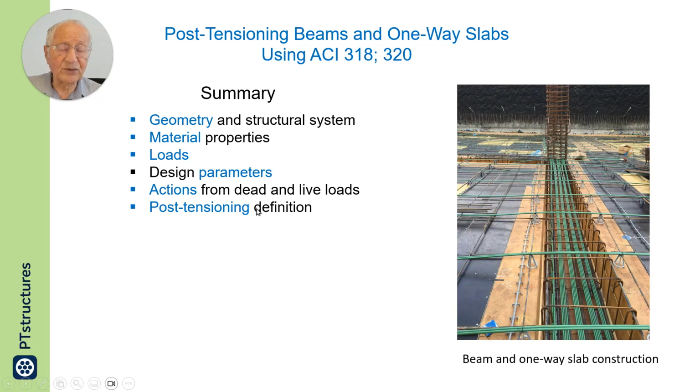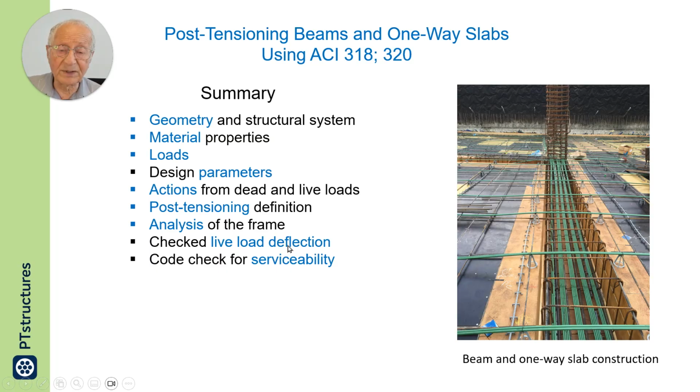We then moved into post-tensioning selection, assumed a percentage of self-weight to be balanced, and calculated the required number of rebars. We analyzed the frame. We checked for live load deflection because, as I mentioned, that is a must-satisfy requirement.